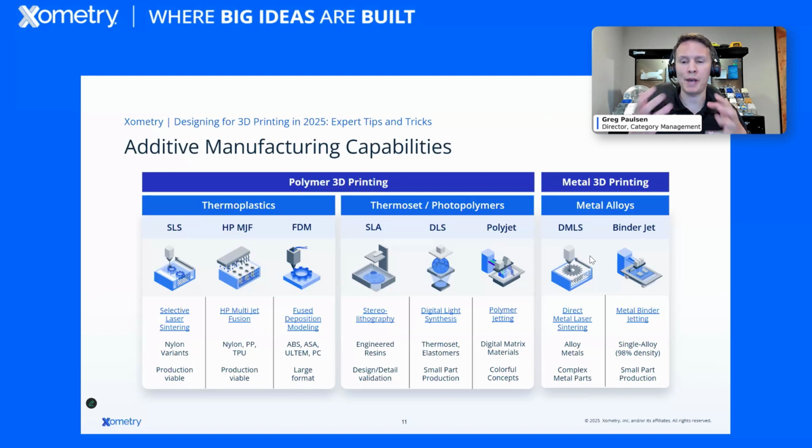Both these metals use a powder-based process, but they have different ways of making the metal part solid. Direct metal laser sintering uses a laser to selectively melt areas on a build chamber and build a part bottom to top with a very fine metal powder, being fused down to a build bed and growing from there. Metal binder jetting uses a glue binder and then has secondary processes, so it'll make the shape gluing layer by layer, creating a green part, and then you go through several stages to take that green part, move it to a furnace stage, and then it'll actually sinter into a metal part.